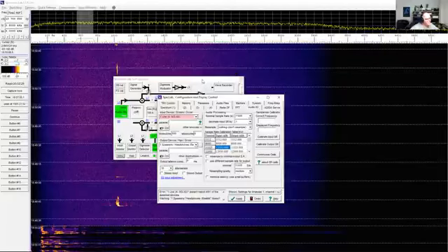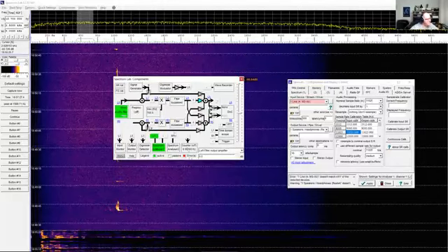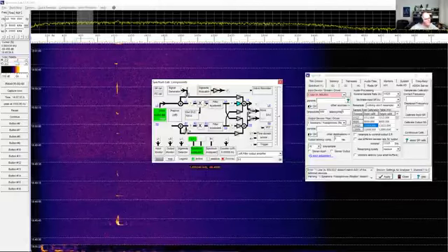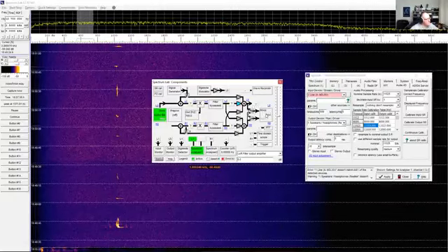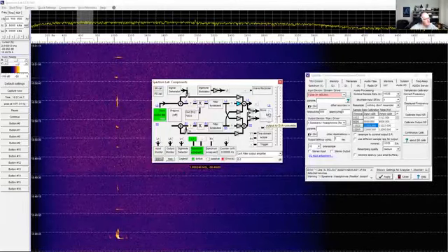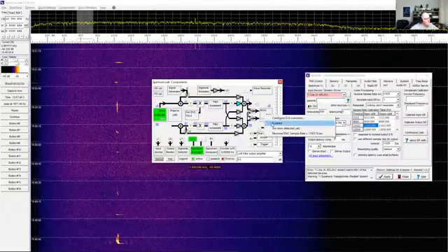And this is almost like a little logical circuit diagram of what happens to the signal. So the signal comes in here, and we're going to bypass the filter, and we're going to come out at this end. And we're going to enable this DAC, which is a digital to analog converter.